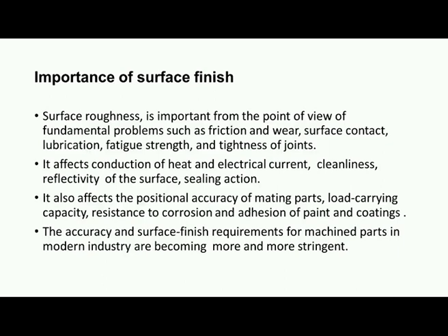The surface roughness is very important from the point of view of fundamental problems such as friction and wear, surface contact, lubrication, fatigue strength and tightness of joints. It affects the conduction of heat and electrical current, cleanliness, reflectivity of the surface and sealing action. It definitely affects the positional accuracy of mating parts, load carrying capacity, resistance to corrosion and adhesion of paint and coatings,